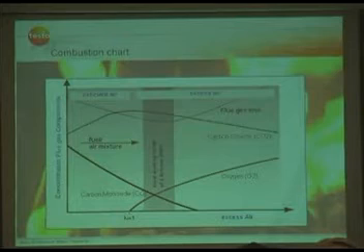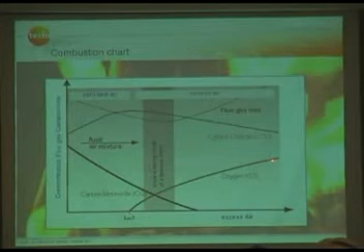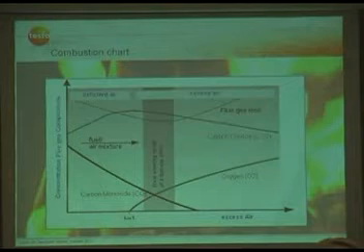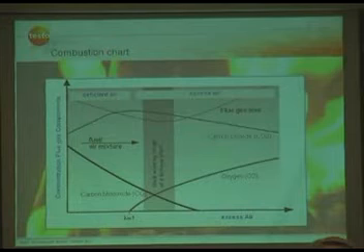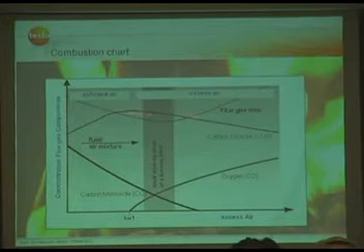On the right-hand side you provide more oxygen than necessary, and therefore the oxygen value goes up, CO goes down because there is no more CO to burn, and at the same time CO2 goes down because of the dilution by the oxygen you provide in the flue gas, and therefore in relative terms the CO2 reading goes down.